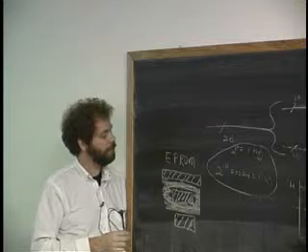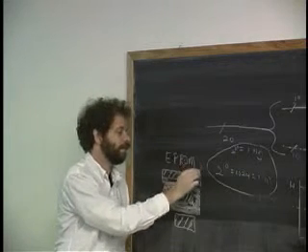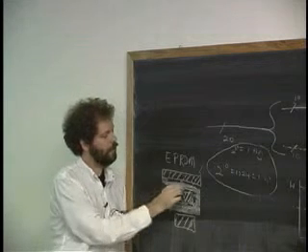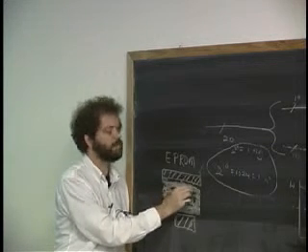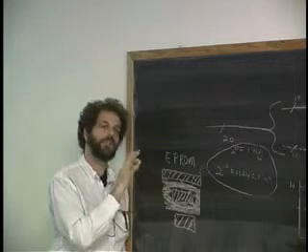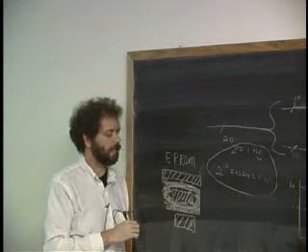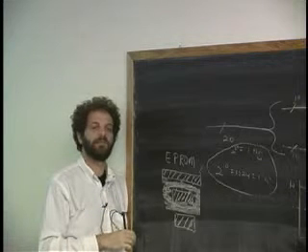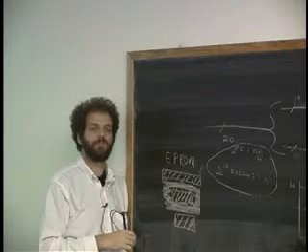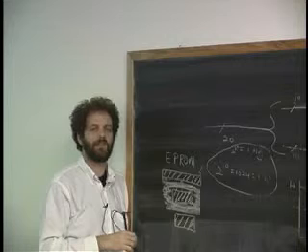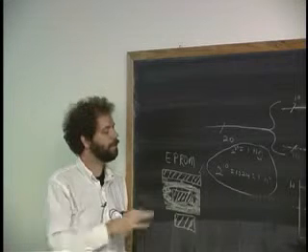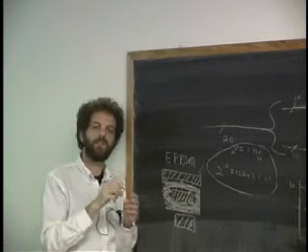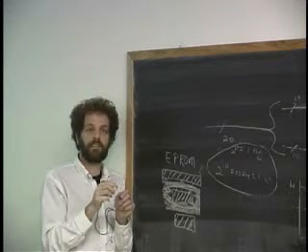And it turns out that another way to do it is if you shine ultraviolet light through here. The ultraviolet light excites the atoms in the glass, and they turn a little bit into a conductor and the charge leaks off. So it makes the glass not quite so good. Is that only while the ultraviolet light is... Only while the ultraviolet light is on. So in general, these chips can be erased with an ultraviolet light, and you see some of them with a window on the top that has glass, right?